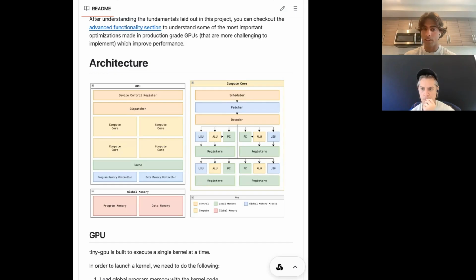And then the second piece of it is in data memory, we're going to load up the actual data that we want to perform computations on. And in this case, this would be like the two 1x8 matrices. We'll call them A and B. So as I said before, A is going to be in addresses 0 to 7, and then B is going to be in addresses 8 to 15. And then we'll say that C is going to be in addresses 16 to 23. So that's going to be our result. Now, currently our result matrix is going to start out with nothing in it.